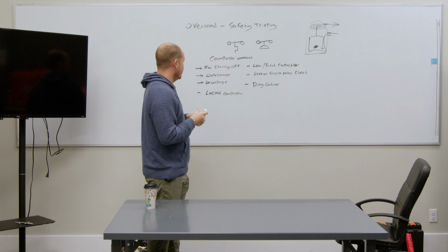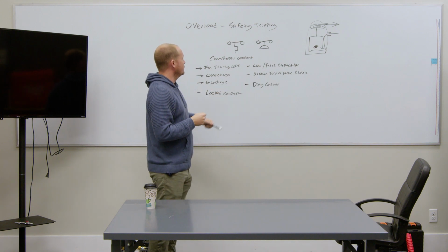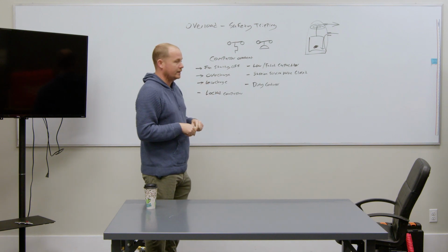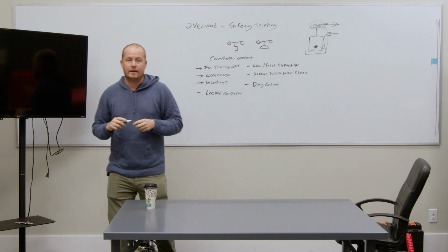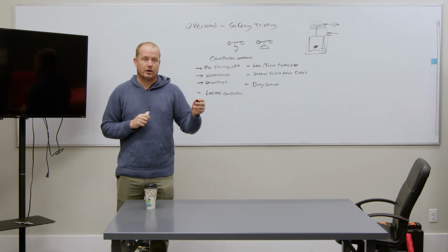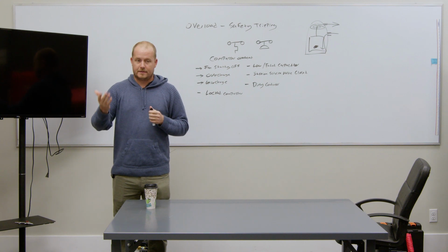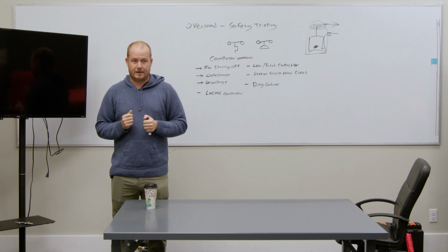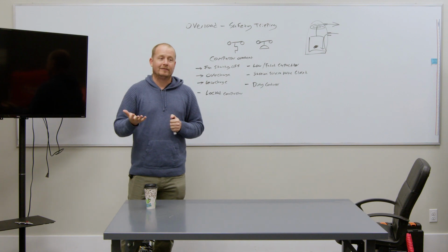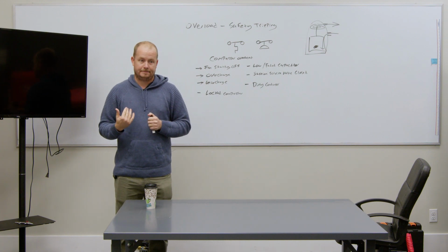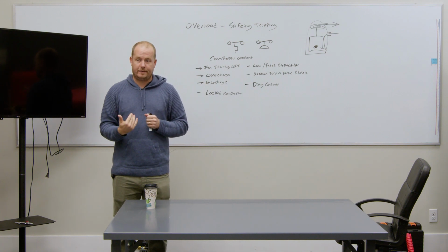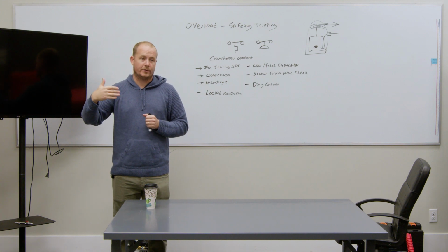So first off, I want to address this quickly before we move on to other safeties, this overcharge and undercharge. So why could undercharge cause a compressor to overheat? Because it's a refrigerant-cooled compressor, right? And so if you have less mass, lower mass flow rate, then your compressor is going to run hot.